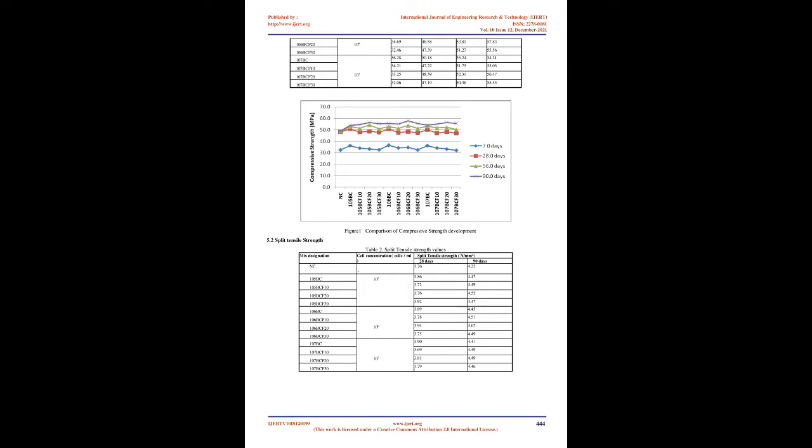Bacterial concrete is a concrete which can be made by embedding bacteria in the concrete that are able to constantly precipitate calcite. This phenomenon is called microbiologically induced calcite precipitation. It has been shown that under favorable conditions, for instance Sporosarcina pasteurii, Bacillus pasteurii, a common soil bacterium, can continuously precipitate a new highly impermeable calcite layer over the surface of an already existing concrete layer.